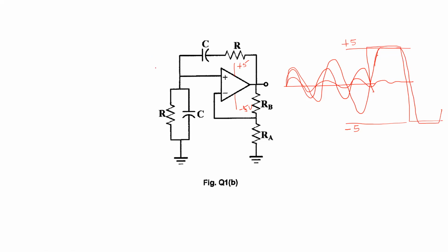So what is normally done in these circuits is that you have to stabilize the output. And we saw that there were 2 ways of stabilizing the output. In fact, there were a number of ways, and that's discussed in the Oscillators 4 lecture. One is to introduce a device called a thermistor as one of the elements in it. So you put a thermistor as part of the feedback resistor. So as it gets warm, the thermistor value drops